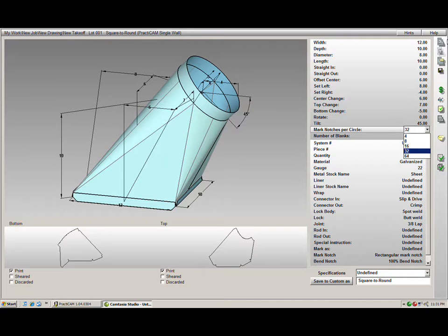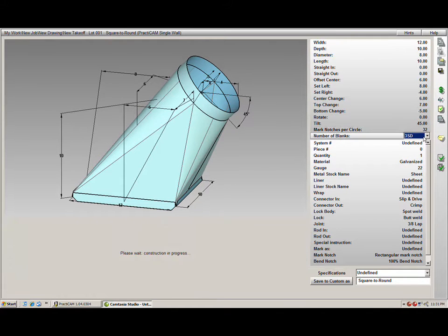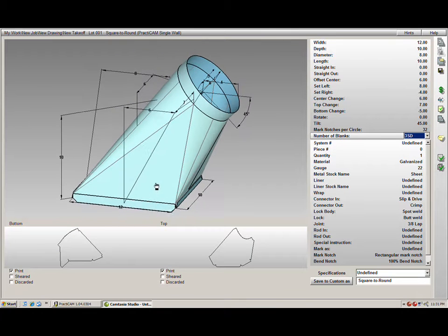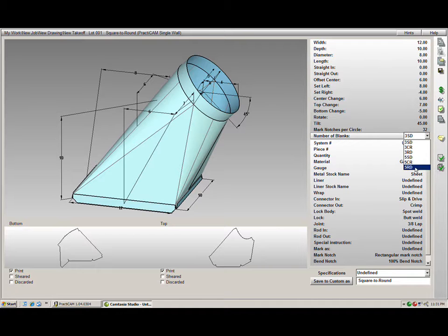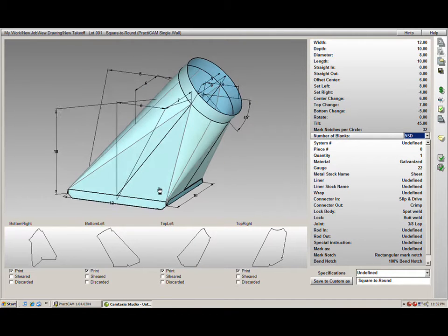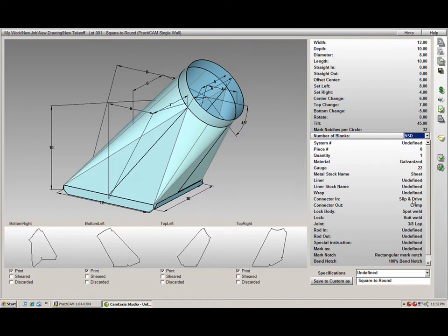After our design is done, you will notice that we can also break down each fitting in any number of all applicable blank scenarios. It is not enough to just have the proper fitting. One transition is not the same as the other. We need to have the right fitting with the proper parameters, and then we need to break it down into the appropriate blanks. For example, here we will pick 5 pieces with side seams. The 5th piece here would be the collar if we decided to add it.